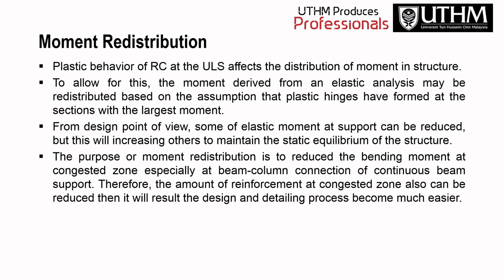Okay, so for moment redistribution, what is moment redistribution? The plastic behavior of RC at the ultimate limit state (ULS) affects the distribution of moment in the structure. To allow this, the moment derived from an elastic analysis may be redistributed based on the assumption that a plastic hinge has formed at the section with the largest moment.